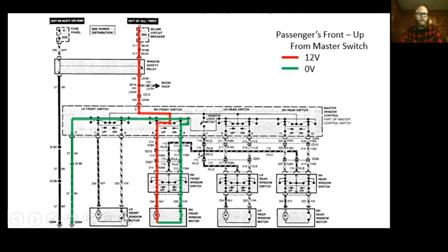This circuit breaker just opens up. When this gets to the end of its travel, it turns into a short circuit because it has really low internal resistance. And so then this, just like a fuse would pop, it's a circuit breaker, so it opens for a time until it cools down and reconnects. And that just keeps us from overheating our switch and our wires. So just like some nice design from the engineers there. Thanks, guys.